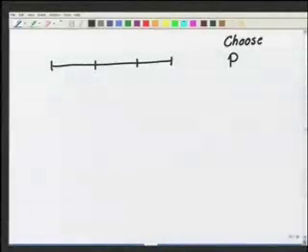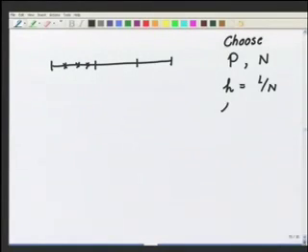Based on the P, now you know P and the N, which is the number of elements. So given N, you know H is equal to L by N if I am using a uniform mesh. So let us take a uniform mesh. H is equal to L by N. Now given the P, I have to put these P minus 1 equally spaced points in each element. So how do I find those points? So I will call something as the H bar is equal to H by P. So this is the spacing between two consecutive solution nodes.